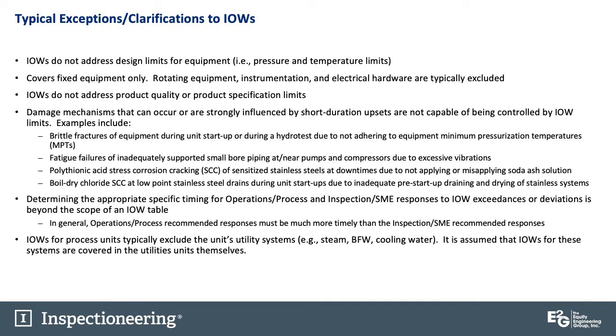IOWs, to this date, tend to cover fixed equipment only, not rotating equipment, instrumentation, or electrical hardware. They are typically excluded. There are some changes I'm seeing in some refineries starting to implement IOWs in those other discipline areas, but fixed equipment only is typical. Why?